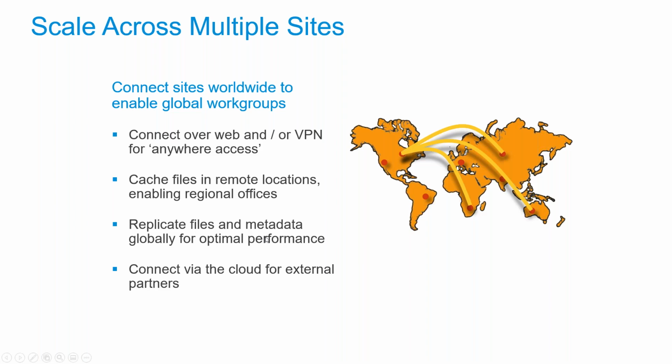Next step up is indeed, well, we've got a database, we've got the files, but let's say that we have a connection which is really unreliable when it comes to web access, to internet service provider access. Then what we might want to do is do a full replication of not just files, but also the database. And then we're going to claim parts of the database, look through that information, open files, all of that locally, and replication is happening automatically and transparently in the background.